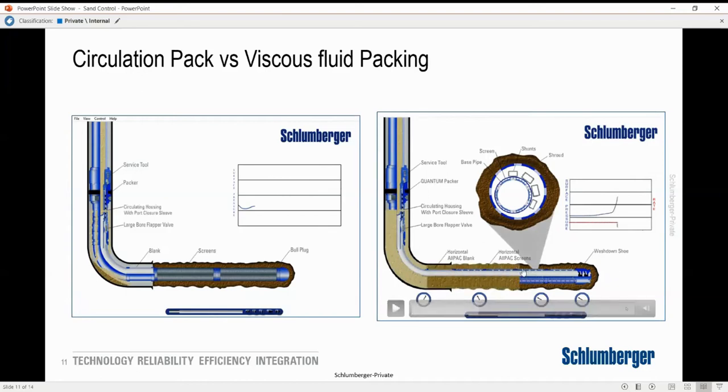So in this scenario, we have described the failure. If you have a loss in certain sections, you will pack all the zones above it, but not the ones below. The advantage of the system is that as soon as you complete this, your tunnels to which the gravel may still travel will pack all the remaining part of the open hole. So this gives you a guarantee of full packing, and with the guarantee also comes the cost.